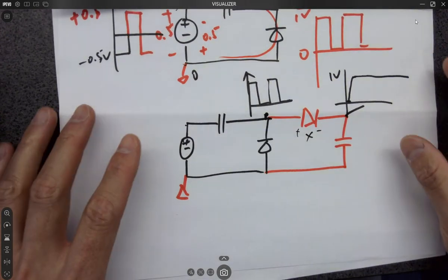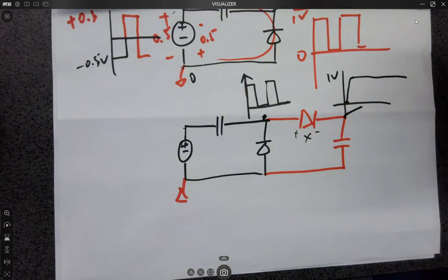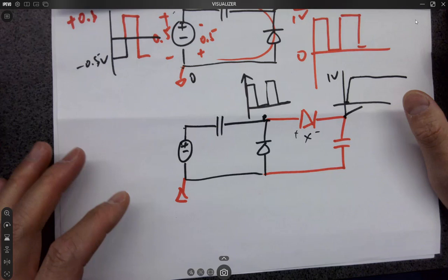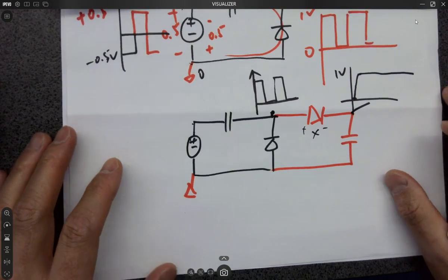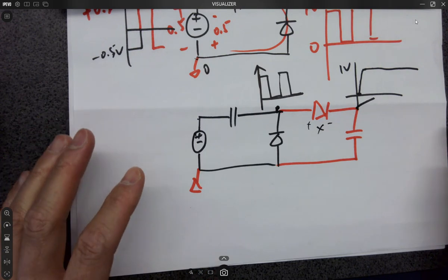So we don't really care about high voltages. Usually it's 20 volts as a maximum. This 20 volts could be quite useful. Sometimes for the memory circuits, the flash, your USB, all the flash memory cells, they are using somewhere around 20 volts to trap the charges to the gates in order to memorize a certain state. That's how that works usually. But other than that, it could be just a little bit above your VDD in order to do your sample and hold.